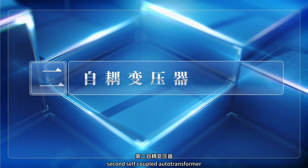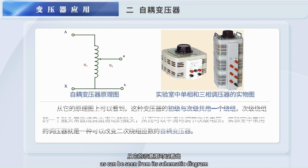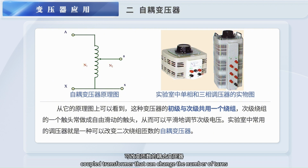Second, the self-coupled autotransformer. As can be seen from its schematic diagram, the primary and secondary windings of this transformer share a winding. One contact of the secondary winding is often made into a free sliding contact, which can smoothly adjust the secondary voltage. The voltage regulator commonly used in the lab is a self-coupled transformer that can change the number of turns.